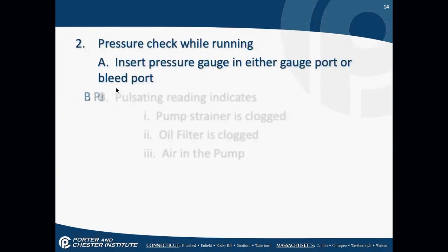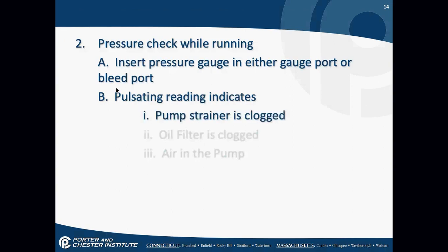We can also do the same thing while it's running. We can insert a pressure gauge into a gauge port or a bleed port. If you watch the pressure gauge while it's running and while it's providing fuel to the nozzle, if the reading on the pressure gauge is pulsating, it means the pump strainer is clogged. We'll talk more about that when we talk about taking apart the pumps.